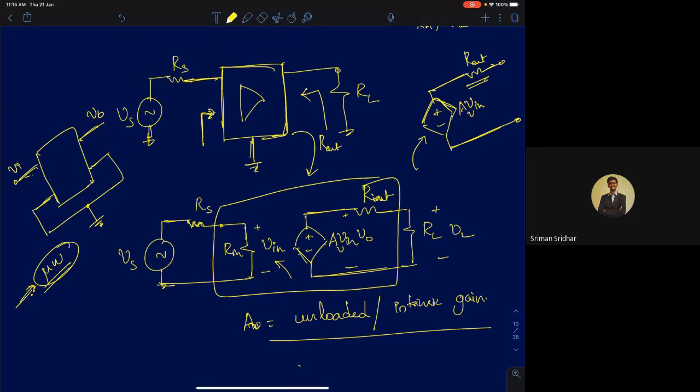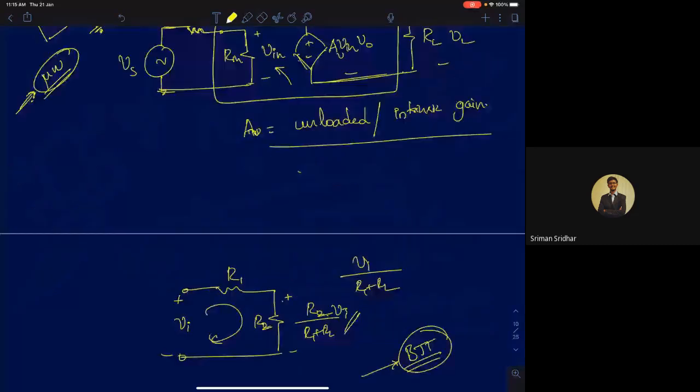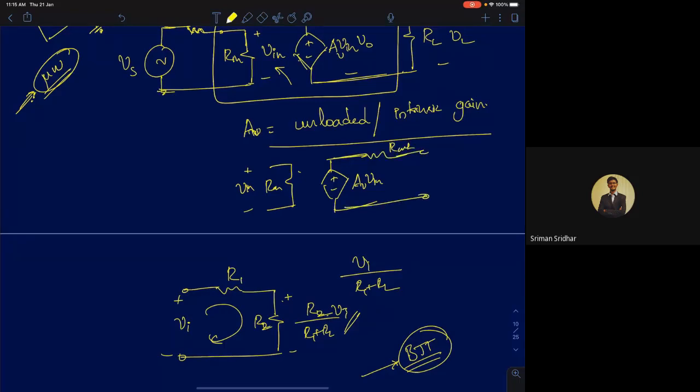Okay, so this is your mathematical model for an amplifier, a voltage input, voltage output amplifier. Input is represented by a resistor. So that is your input voltage. The output port is a dependent voltage source, AV times V in. AV is the gain, and R out is the output resistance. So this is your two-port model.